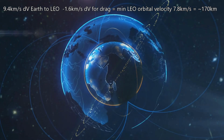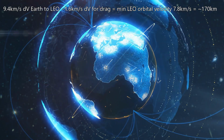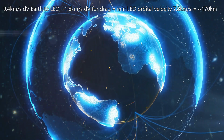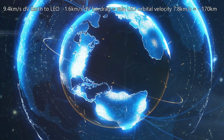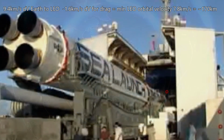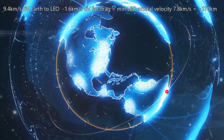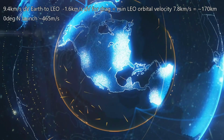There are also ways to increase delta V without burning more propellant. You might plan to launch your rocket from or near the equator, maybe to put multiple small Earth observation satellites into low Earth orbit. The European Space Agency has a launch site just 5 degrees north of the equator. Or you could launch from a ship, like the space company Sea Launch used to, using Ukrainian-built Zenit rockets. Here, the spin of the Earth to the east adds about 465 meters per second. So we could budget a little less than 9 kilometers per second delta V, or get more mass to orbit if we launched at the equator.